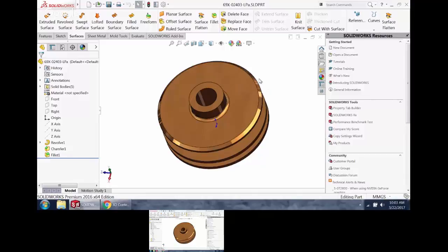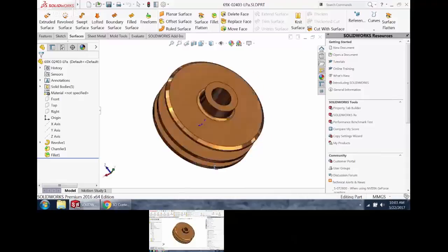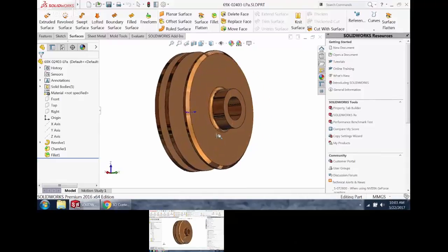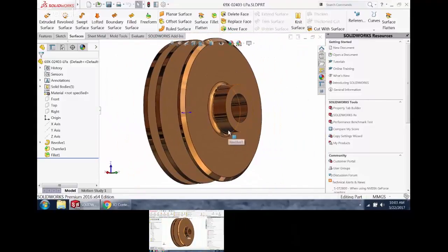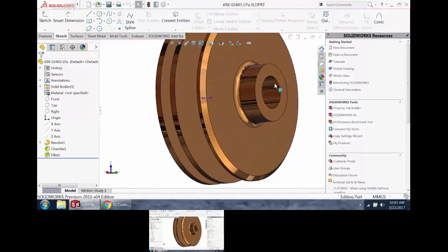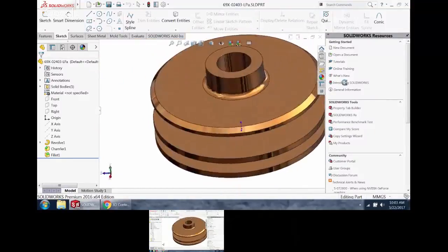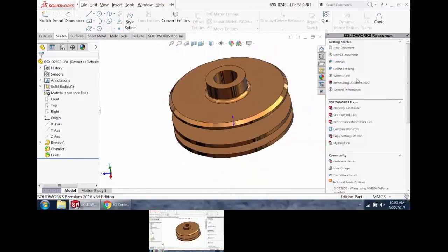There are combinations of keyboards that you can use with that middle mouse. So just pressing it in and moving it around rotates. If I hold the shift key, it's a zoom to center. So it's going to the center of the screen, as opposed to when I'm zooming towards the mouse, it's going to what I'm pointing at. This is going towards the center of your screen. Shift key with the middle mouse is a pan, and the Alt key with the middle mouse is a flat spin. So with those keyboard combinations and that middle mouse button, you can move this thing around pretty wildly.